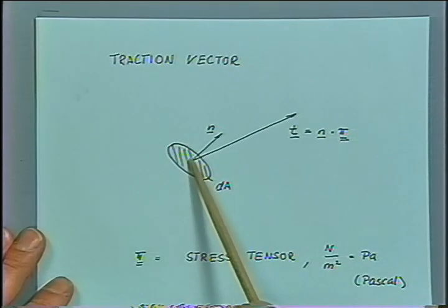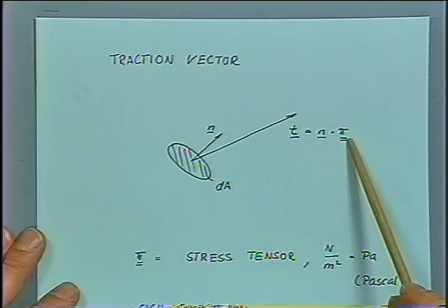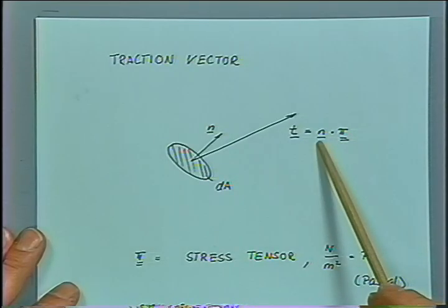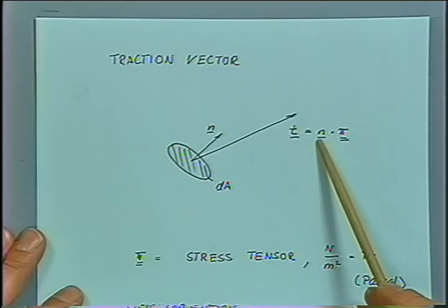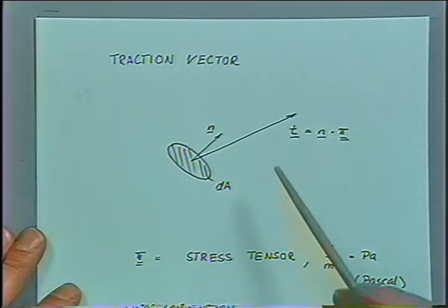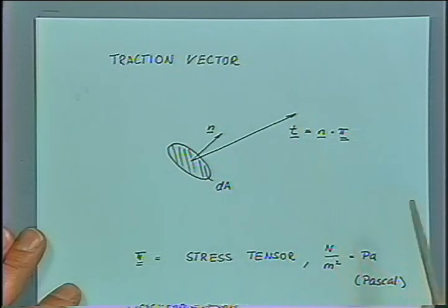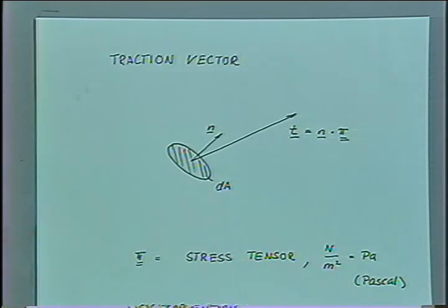The stress locally is defined by the stress tensor. If we know the stress tensor, then we are allowed to pick any n, any direction of our infinitesimal area element, and we can calculate the associated traction transmitted through. And remember, we needed 3 of those tractions, or 3 area elements at point P, to have a complete description of the stress, to have all components of the stress tensor.